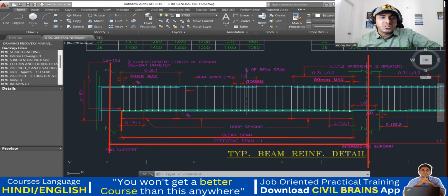Near the support, you'll be providing your stirrups at a very close distance to each other. You can check here also. They're very close to each other, right? Why is it so? Because near the support, the shear force is maximum, and also because from earthquake detailing we are supposed to do so. In the center portion, the spacing is increased. Understood? This much is understood.